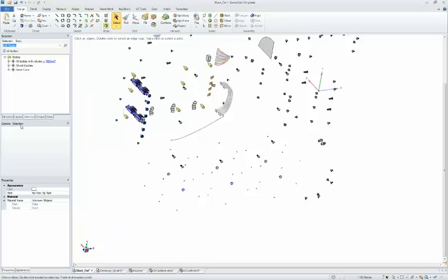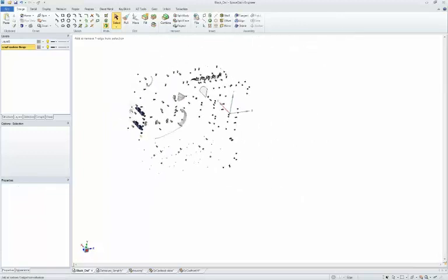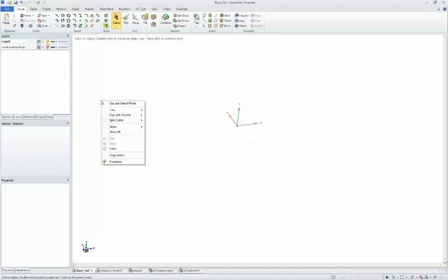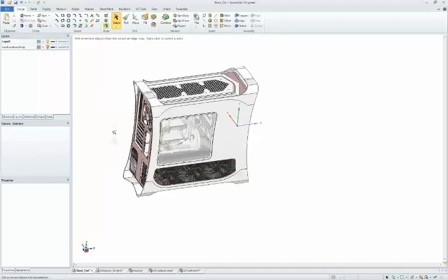But what I also might want to do is just save them. Put them on a new layer. Kind of organize that model for analysis. And just call this small, useless things. I mean, maybe I want to take one or two things back and add it back into my analysis, but for the most part, I probably don't need these. So why not put them on a layer, hide them, tuck them away, and if I ever need them, I can go back to them.